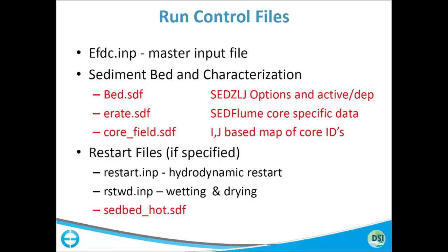of EFDC and SEDZLJ. So if you run the model and the model crashes, for whatever reason you want to restart it at the last snapshot of your restart files, you can do that with the SEDZLJ here. And with EFDC Plus, you now have the ability with run continuation, which was not available before. Like if the model's running, it crashes, you lose power or whatever, and you've turned on restart.